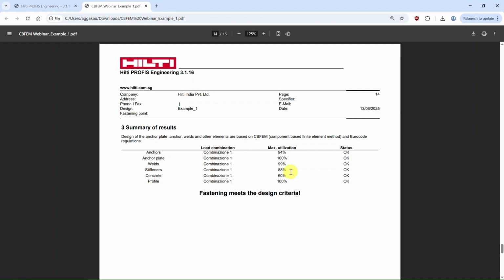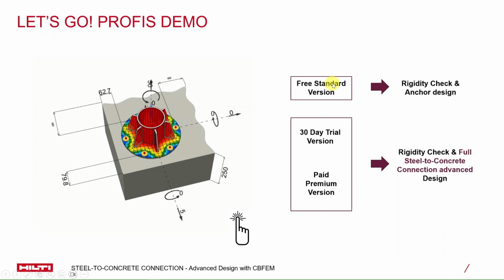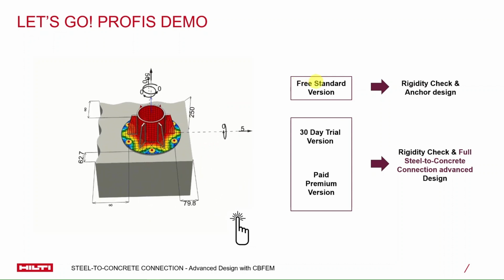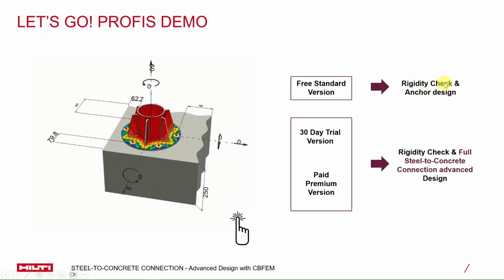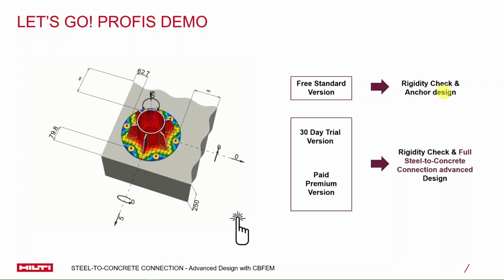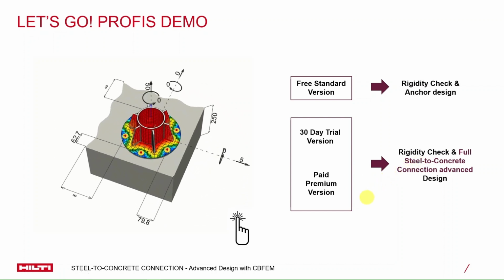So even if you have, in conclusion, the standard version or the premium version, the major difference is basically if you already have your base plate size and the thickness fixed and you just want to check whether that's stiff enough, then you can still utilize your standard free version to do the rigidity check and design the anchors for the elevated loads, if any. But in case of premium, you can do the full base plate design along with the stiffeners, welds, etc.